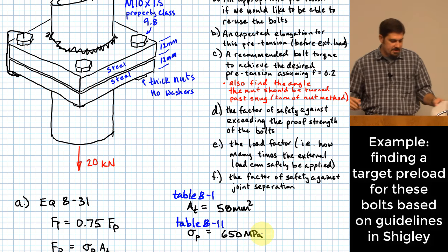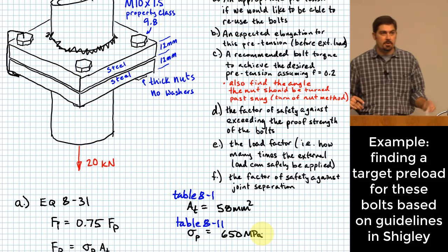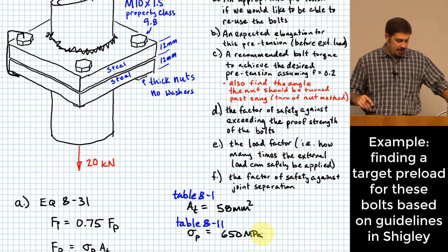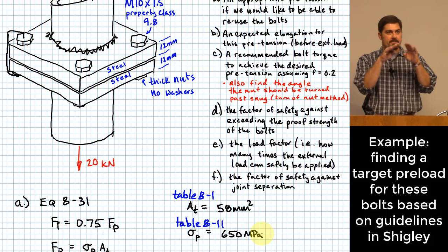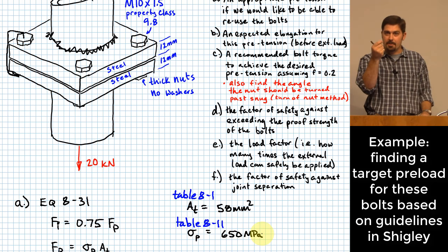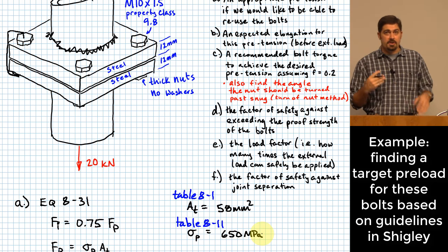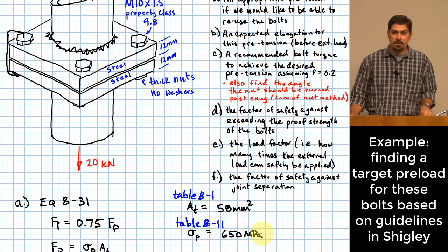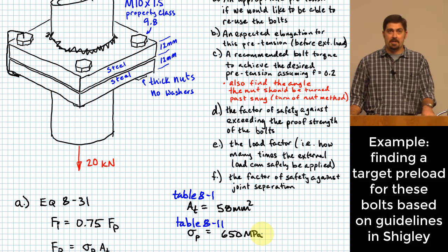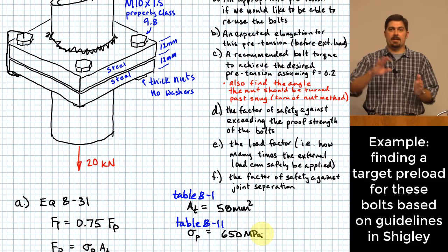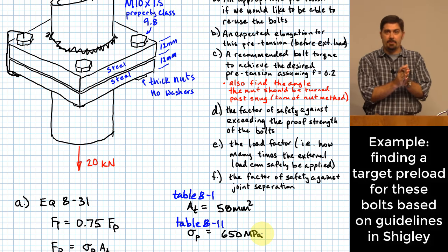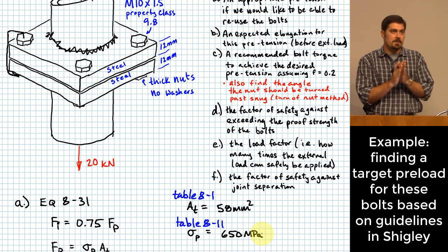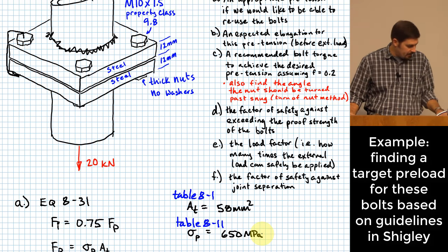One way of thinking about this is that always material properties like this, strength properties, they occur as a statistical distribution, not as a deterministic value, right? And so when you're designing stuff, you typically want to make sure that even if you've got the weakest one of the batch, you're still okay, right? And that we kind of almost ignore the fact that a lot of them might end up being stronger than this. We just basically say we want to make sure we're safe even if we got the worst one, all right? So that's why we have the word minimum in the heading of that table.